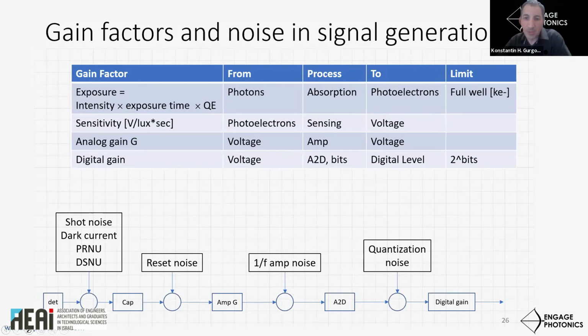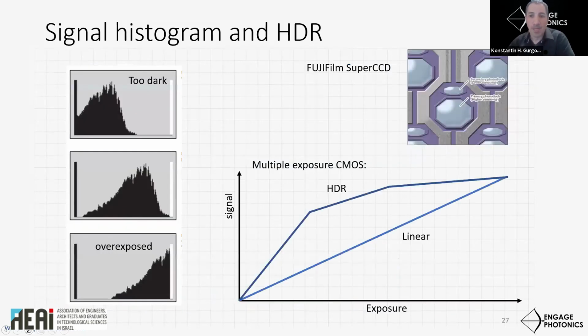It is important to control the image sensor in real time, especially the exposure time and analog gain. The rule of thumb is that you need to allow maximal permissible exposure time without causing motion blur. And if the image is too dark, apply analog gain. Digital gain has zero effect on SNR, and it has little effect for computer vision applications. So a saturated signal is useless.